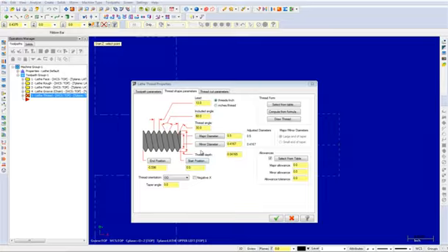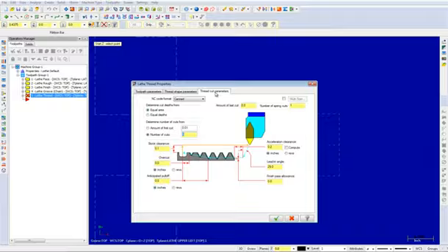Now, select the Thread Cut Parameters tab and ensure that the NC code format is set to canned. Enable number of cuts and input a value of 5. I will now explain in further detail what each button does. NC code determines the output of code displayed in your NC file. Determine cut depth determines how the material will be removed.